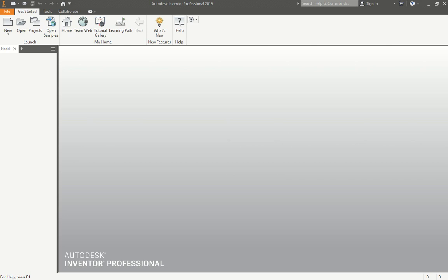So the top-down assembly is where you have the assembly file, and you create it first, and then the components are created in there. So top-down means you start from one piece, and you build off that. The other one is the bottom-up approach. It's what you guys just did now. We built all the pieces, and then we're going to assemble it. The middle-out assembly is in between both. You start with some, build off that, and then some of them you bring in as well. So in most cases, you're going to use either the top-down approach or the bottom-up approach.